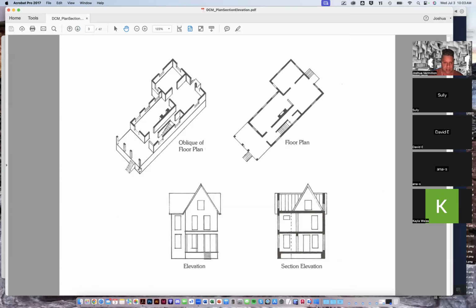We can turn that floor plan and then project up to create an axon or a plan oblique. Again, we can slice the elevation open, like this front elevation down here, and create a section. They call this a section elevation. I don't understand why. It's simply a building section where you can see the foundation, the floors, the walls, everything that's being cut through. Beyond, you do see elevation information. Anything you would see beyond that section cut, edges and windows and things like that, are typically drawn.